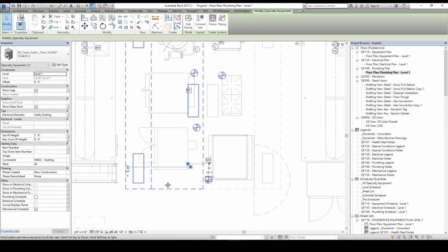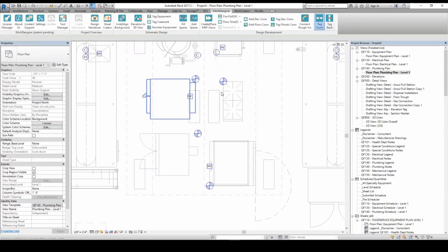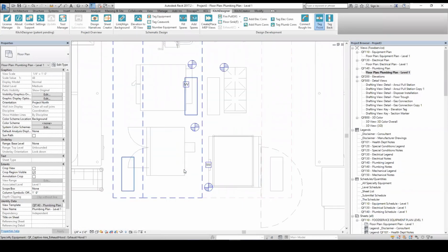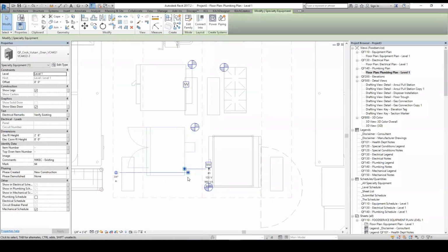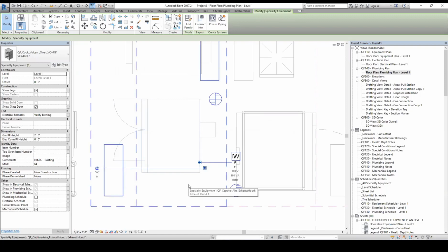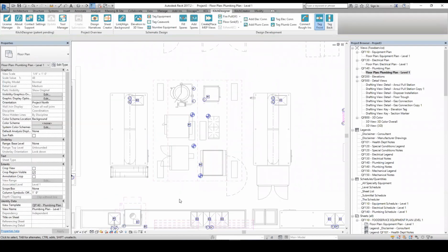These did, obviously, we saw that, but if they did or they didn't, and they had maybe the wrong type, at least this way you have a standard gas location that you don't have to worry about. So this came up recently just because I've noticed there are a good bit of families that most of the connectors are great, but sometimes gas connectors end up in hydronic supply, which is the default system type. And I think that's probably because some content creators don't understand to set it to other pipe, unfortunately.